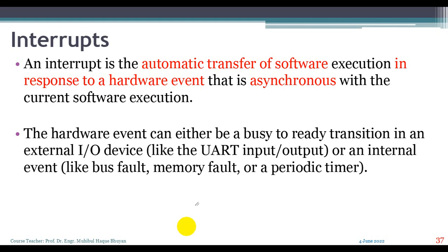So, in a software approach using the microcontroller, how do we do it? We use a sensor called a PIR sensor to sense the presence of a human. How does this sensor work? When the sensor senses the presence of a human, it sends a high value to the microcontroller pin. When we get a high value in the microcontroller pin, we take the necessary action. That means we turn on the AC.